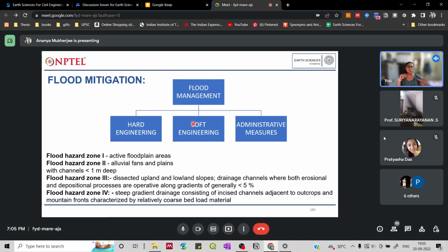Then, as we talked about natural levees, you can build upon these natural levees artificially, or you can create embankments next to the river channels, so you can hold the excess water due to an increase in river discharge. And then you also have something called flood walls. Now these flood walls are not waterproof and not very sturdy, but they can also be constructed.